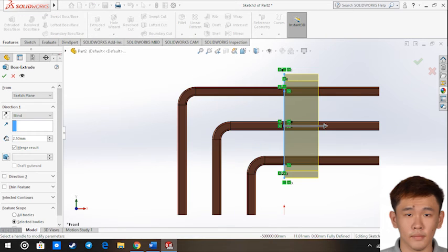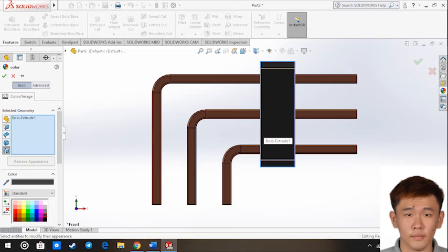After that, choose Sketch 3 and click on Extruded Boss/Base function. The depth is set as 2.5 mm. Then choose the Boss Extrude 1 object and click on Edit Appearance. The color chosen for this object is dark gray.